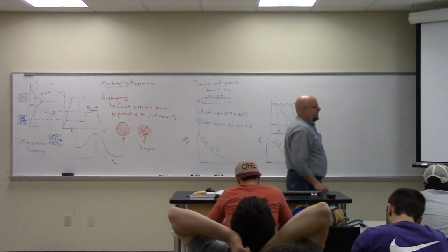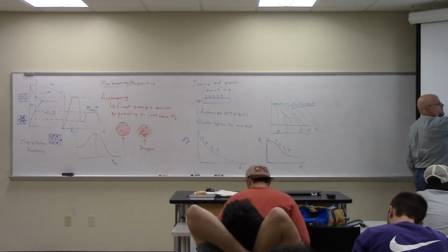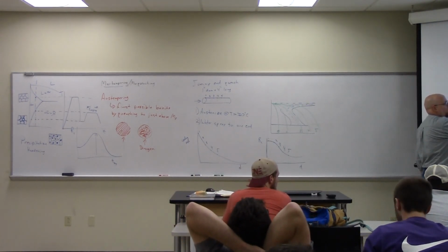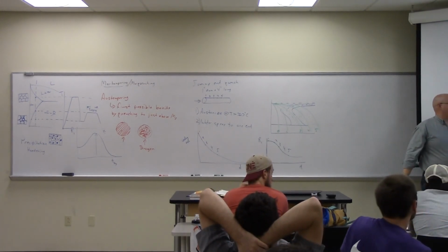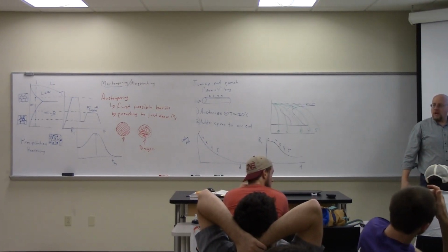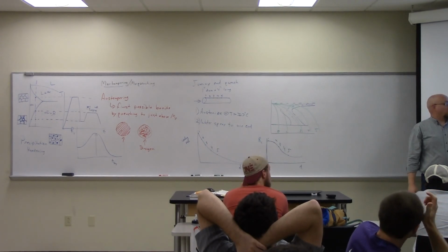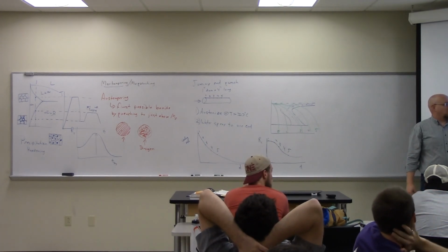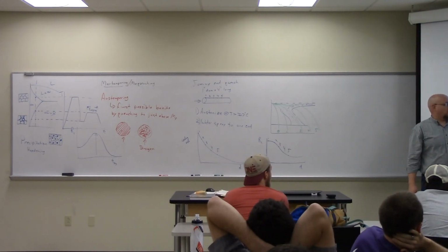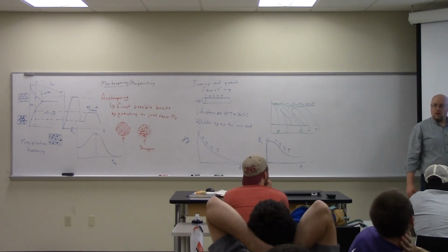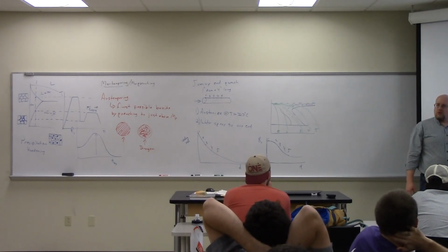So basically, if we had a curve that went like this, then its furthest intrusion, in other words, if it just kisses off the dashed line, then we'd say we have 50% medium pearlite, somewhere between coarse and fine, whatever this area is, right? And then the other 50% would be transformed into martensite.